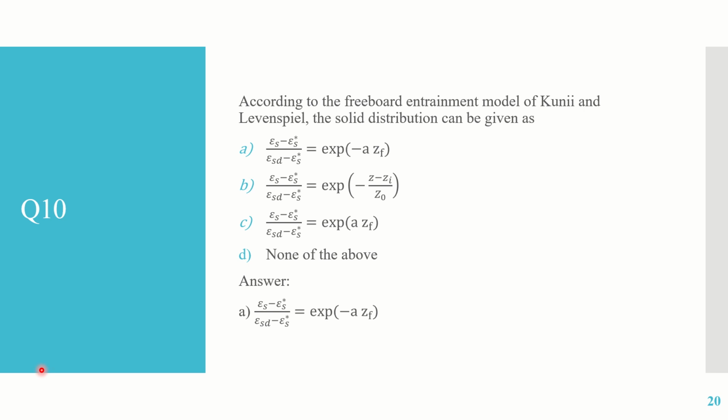The first phase is the gas stream with dispersed solids in it, the second is the agglomerates coming from the bed which are moving upward, and the third is the agglomerates plus a thin layer of solid particles which is moving down. So initially there is a gas stream carrying some portion of solids to the upper region, then agglomerates coming from the dense bed moving upward, and the last one is agglomerates coming along with a thin layer of particles moving downwards.